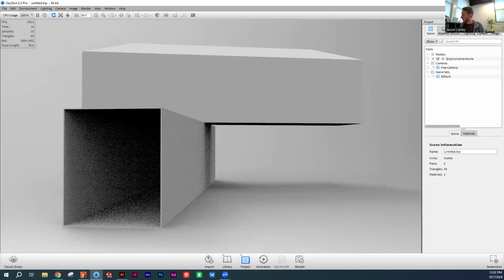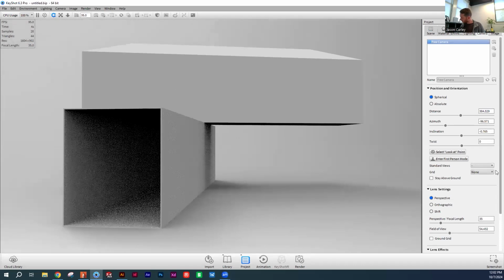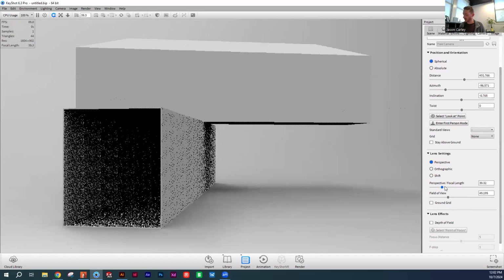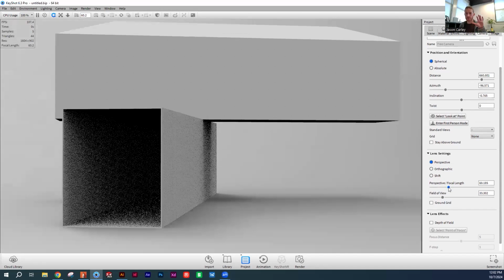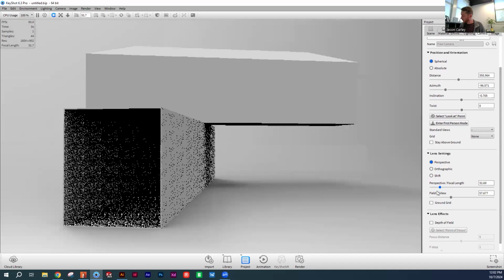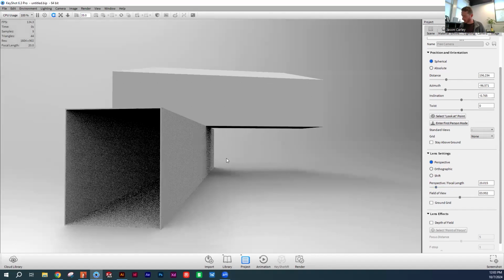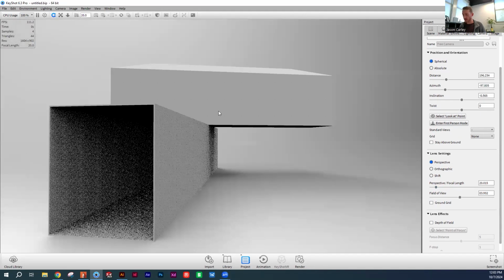So I do that by going to camera. Perspective mode is on. And you can change the perspective or focal length here in this setting. So this is the setting that you want to find. Counterintuitively, the higher number means that there's less perspective shift. The lower number induces more perspective. This becomes more dramatic, more foreshortening. Hopefully you guys can see that.